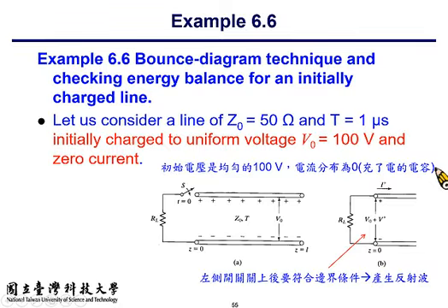After the switch is closed, if R_L is not the same as Z sub 0, there will be a mismatch. That is, the voltage over current ratio across R_L is not equal to the ratio Z sub 0. Because a resistor of 100 ohm means that the voltage over current ratio should be 100. All right.